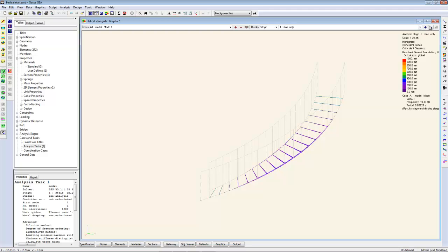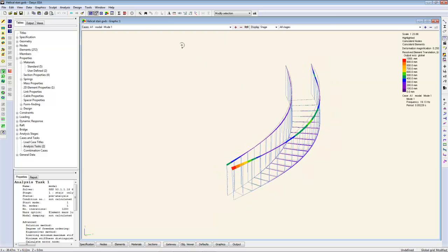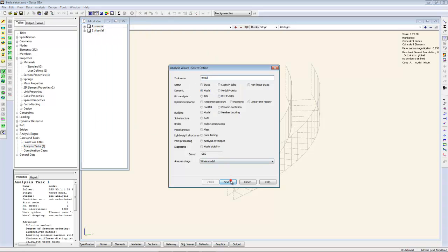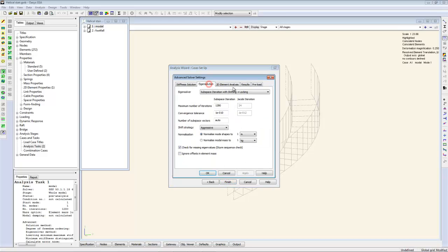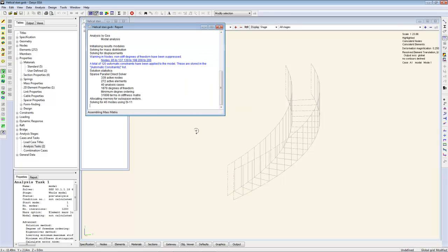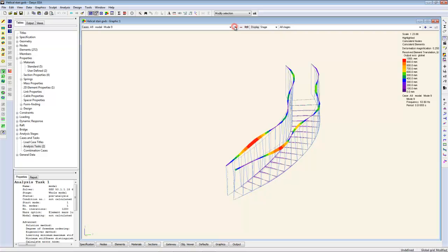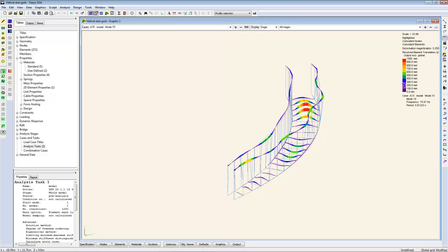now the first mode is actually lower, but the vibration is really looking at the balustrading, and we need to get considerably more vibration modes. Let me just check, are we? Yes, we have read the new method. And the first frequency when the staircase itself starts to vibrate is, there we go. Now the first frequency there is about 75 Hertz, because the balustrading acts like a deep beam.